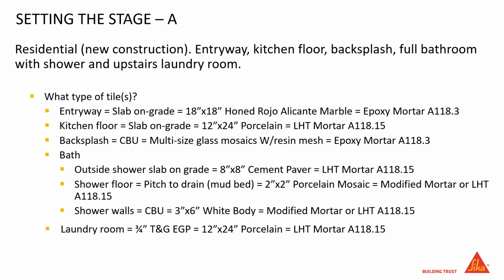Now, I know, and I'm sure a lot of y'all know out there, green marbles and red marbles can have a tendency to be very water sensitive, and either loss of bond or potato chipping. But there's also another thing with Rojo Alicante that I mentioned before. Sometimes Rojo Alicante comes with a netting on the back of it that is resined to it, because that crystal vein that runs through it can typically be an easy breaking point during shipping. So by looking at this marble, we know that there's some characteristics to it. We're going to go ahead and automatically assume that it has that netting with that resin on the back of it, and we're going to recommend, or we're going to be using, an epoxy mortar, 118.3.